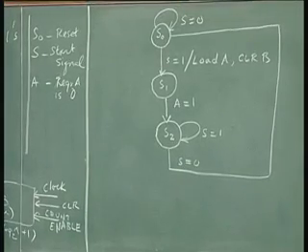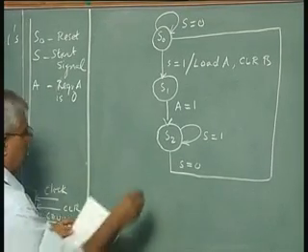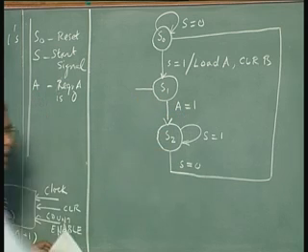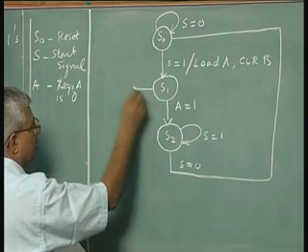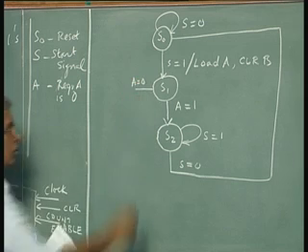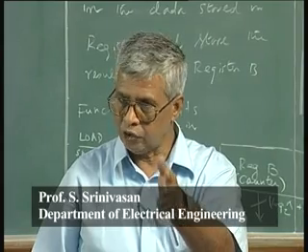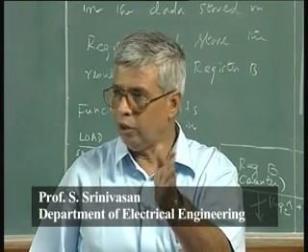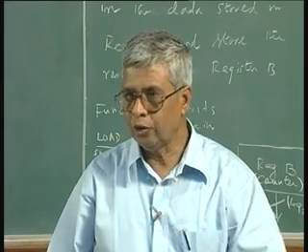I am going to look at the LSB. So, I am going to see if A is equal to 0, that means the value of the register A is 0. A is 0, that means A is not 1. Then I have two choices. I look at the LSB, which is 0 or 1. If 0, I do not count, but I shift. If it is 1, I shift and count. So, I have two possibilities.